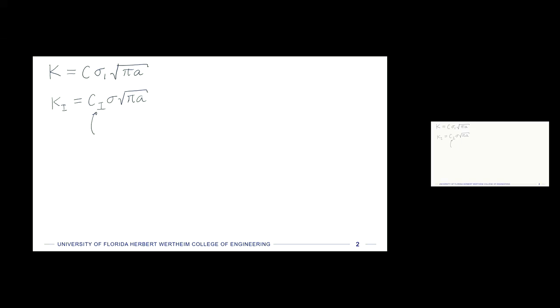No. For some reason, the book introduces multiple forms of equations that all have a constant C out front, so no, it is not. This geometry factor helps us to translate how those faraway stresses affect the local crack tip stress.